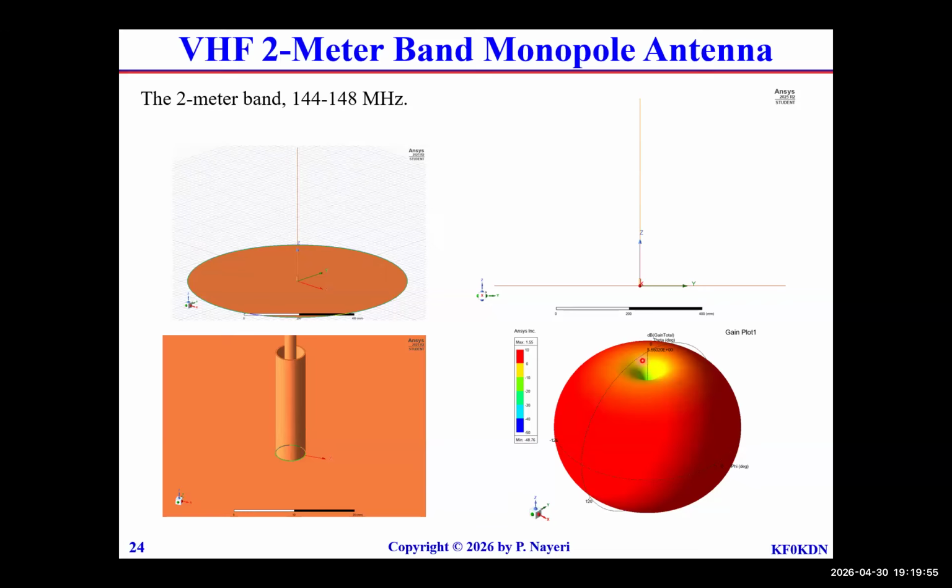Very good. And this is the radiation pattern, as you can tell. Note that the ground plane here is extremely small. For a typical monopole antenna, in order to get a good radiation pattern and a good directivity out of it, you typically need the ground plane to have a diameter of at least 5 wavelengths. So this is extremely small, but it does something. And you can probably experiment with it once you open the HFSS file.